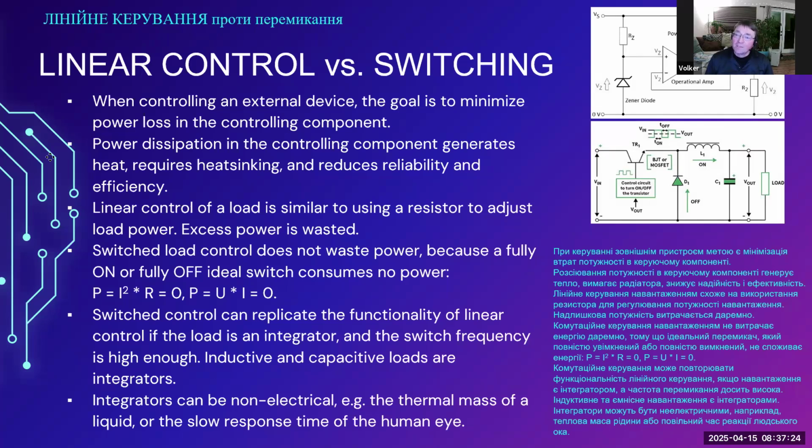In that case, the power transistor essentially is designed or intended to waste the heat, or to waste the energy that is being generated by the difference between the supply input and the intended supply output. Linear voltage regulators used to be very common because the implementation of switched voltage supplies was difficult. It is not difficult anymore.